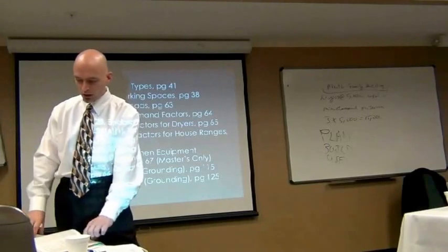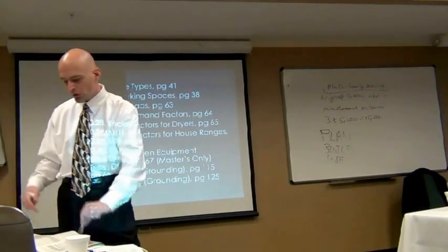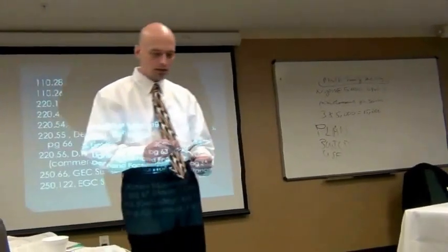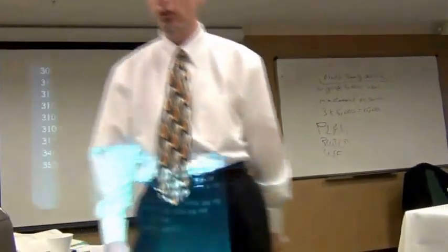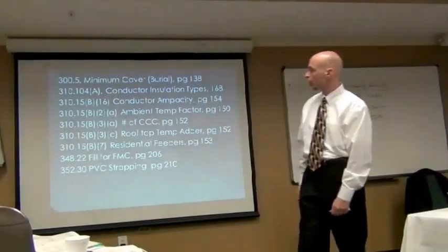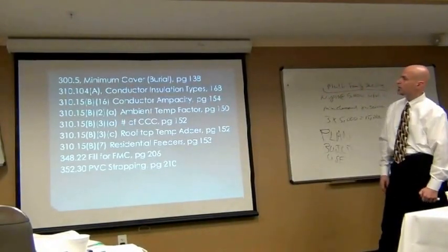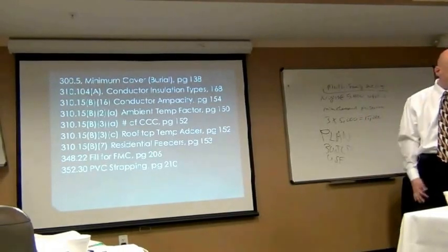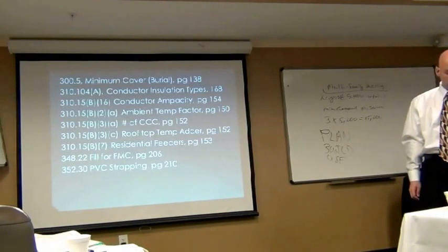And that, in a nutshell, that's grounding electrical conductors, equipment grounds. There's a few other questions that kind of come in and out, some of them under 250.118, but I've got them listed on a separate page. All your tables under 300 are all, I think, on your page there. I don't think we've added any of them or changed any of them. Under 310.15, B16, we're going to go through that here in a little bit, and that's going to have quite a few changes as far as the actual table layout.